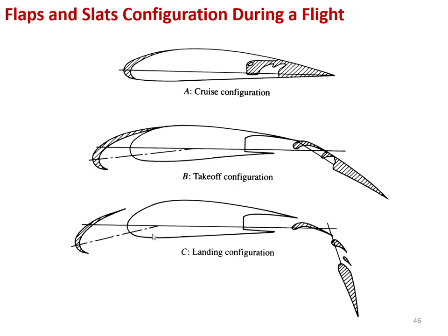During the landing, where you need a lot of control, when you have to be able to control your flow, this is the configuration. Combining all of these together is going to help us control the stall conditions, control the movement of the aircraft. It's not just about increasing the lift and delaying a stall, it's more about control.